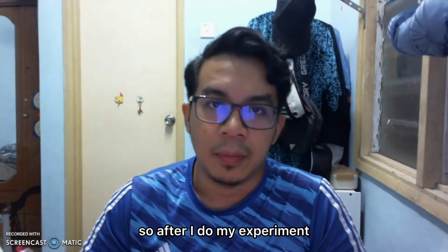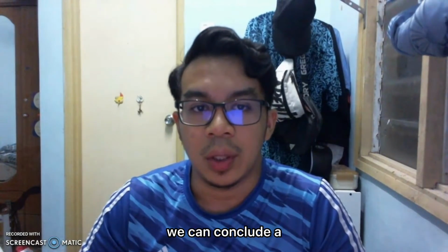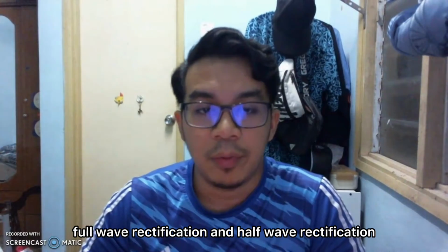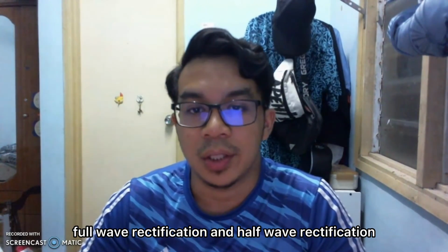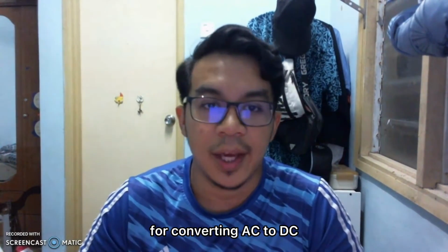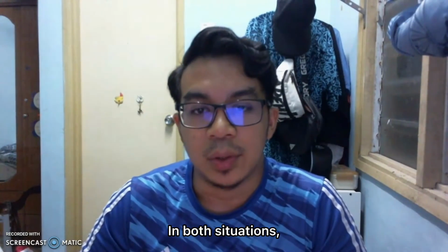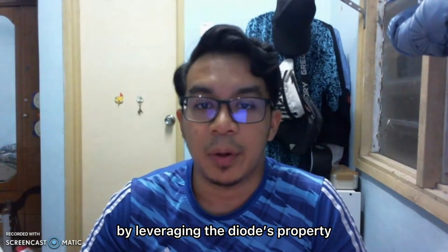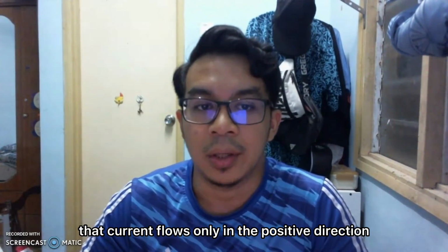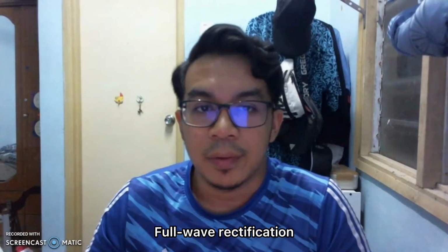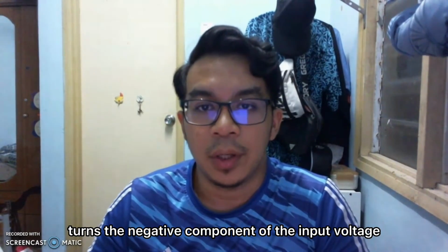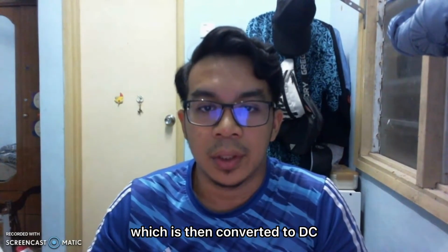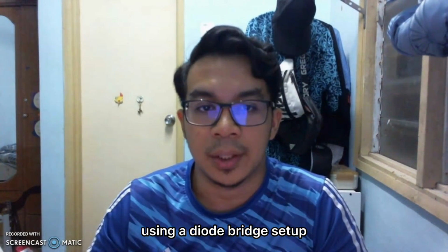So after I do my experiment, we can conclude difference between full wave and half wave. Full wave rectification and half wave rectification are two ways for converting AC to DC. In both situations, the rectification is performed by leveraging the diode's property that current flows only in the positive direction. Full wave rectification turns the negative component of the input voltage to a positive voltage, which is then converted to DC using a diode bridge setup.